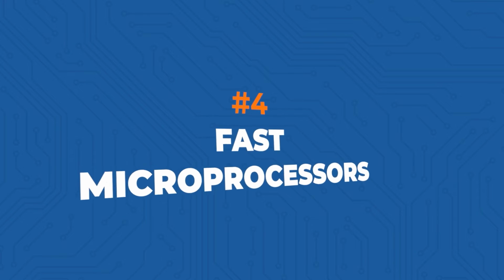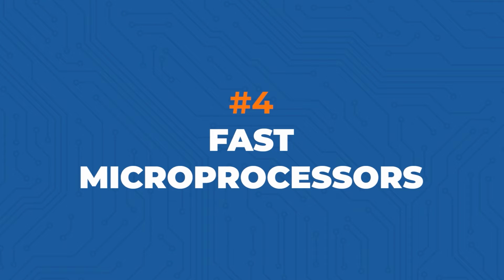And then fast microprocessors that have external RAM memory, for instance, can be more complicated to lay out. It's quite a bit different than laying out a microcontroller, because with a microcontroller, all the really high speed stuff like the RAM, data bus, and address bus are typically internal to the microcontroller. It's something you don't have to deal with as the PCB designer. But for a microprocessor, the RAM is going to be external. It's going to be on a separate chip on the board. You're going to have a data and an address bus.